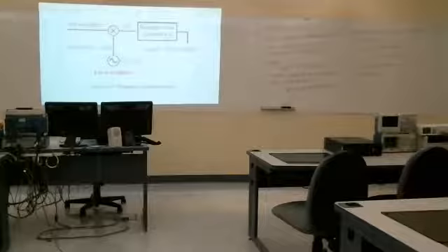Now, I kind of led you to believe that the way you do channel selection or station selection is you bandpass filter around the station that you want. Filter out everything else. I mean, that would kind of work, right? In our AM receiver, we turn a tuning knob that's adjusting the center frequency of a bandpass filter to pass through the station we want to listen to, envelope detect that, and we're all set.